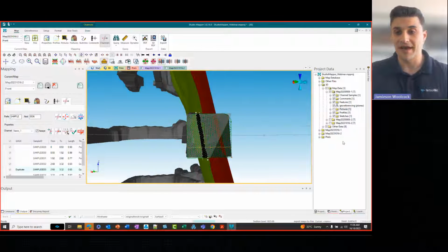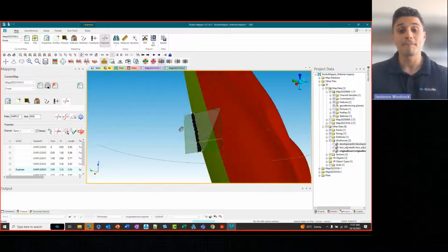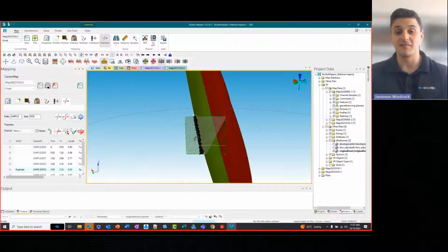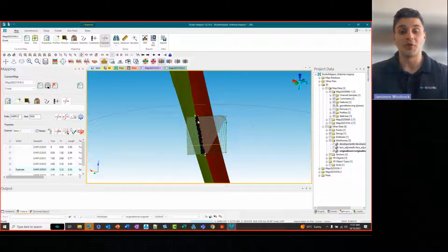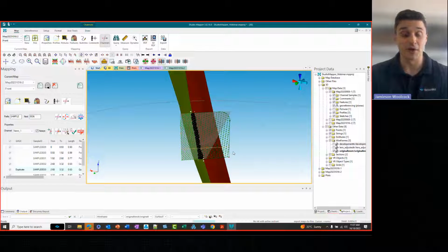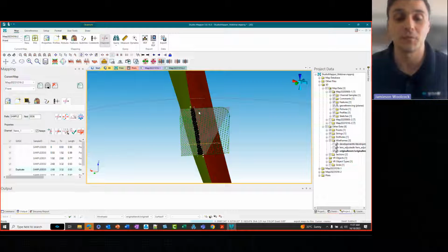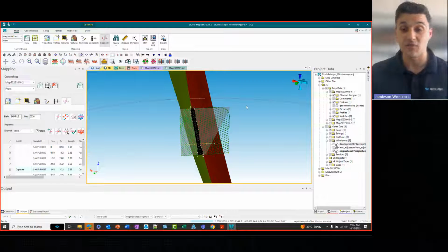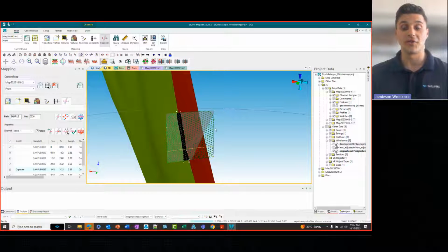So here we've got a map that was made previously. We've got an ore solid wireframe. Obviously we can see maybe this was taken, we didn't have a drill hole going exactly through there. What we've observed is quite different from what we've previously modeled. Now in RM, you can take these footwall and hanging wall strings and use them with the implicit modeling vein tool to force your wireframe solid to go through those lines.